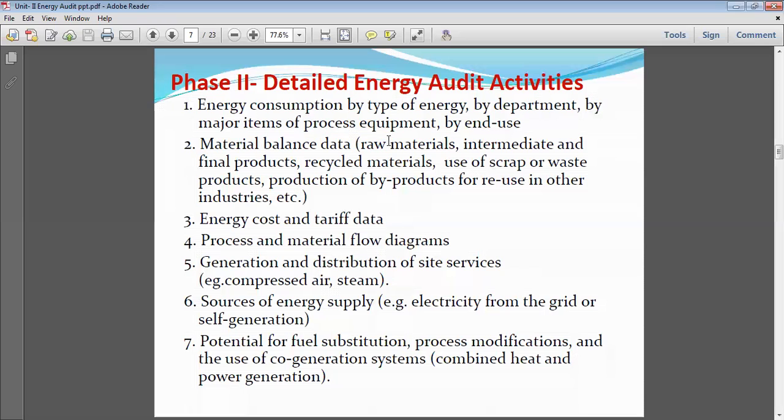If you use below that required value, definitely your compressor will remain on. It will consume more power. So therefore, we have to compare with the standard or the recommendation, or as per the manual or guideline given for the different processes. In that process, the temperature needed is 15 degree, but they are keeping it at 10 degree.